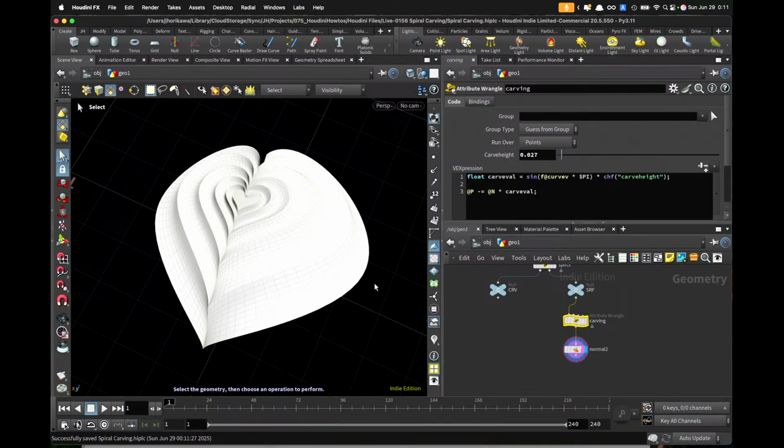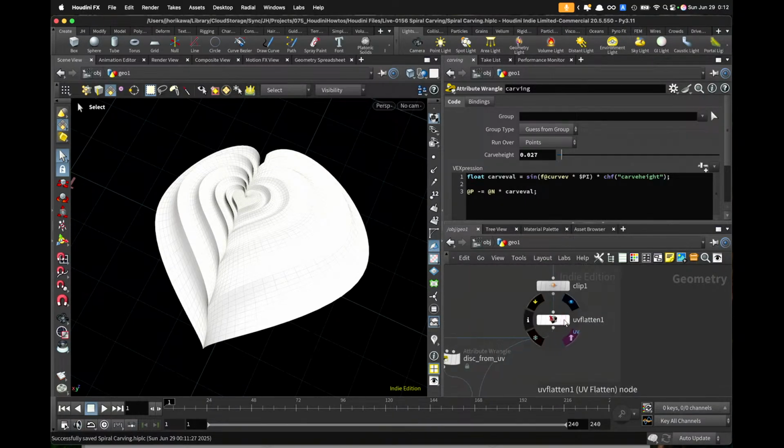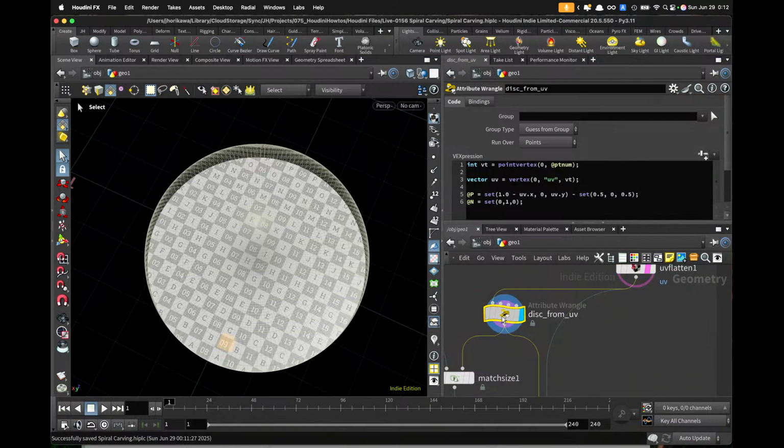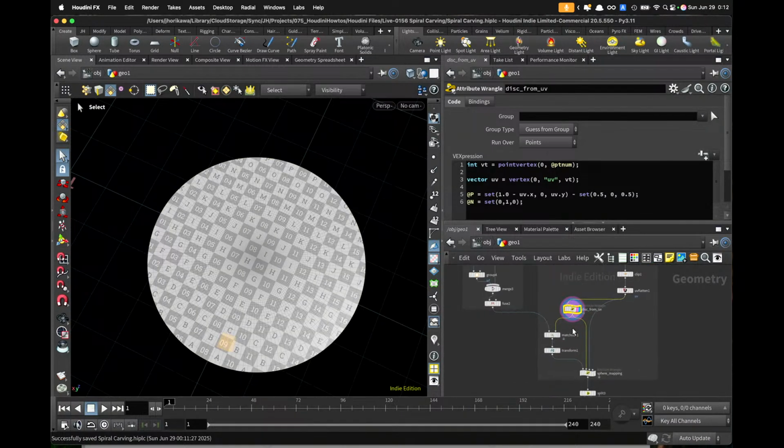I mean, you need to recalculate the lengths when it's being mapped, but it is going to create some issues when using animations. So the best way is to try to calculate the lengths before mapping the surface and just forget about the layer width difference for a UV mapped result.